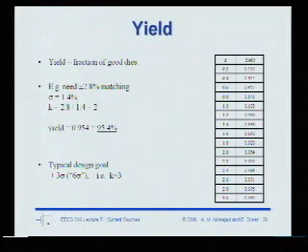Let's say that you need 2.8% matching to use this example. In other words, as long as the mirror currents match within 2.8%, then the part satisfies the specifications. And you've designed a current mirror that has a match of 1.4%. That's good, right? What's the yield going to be?